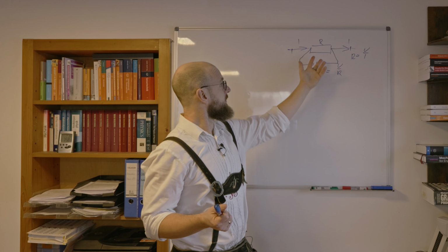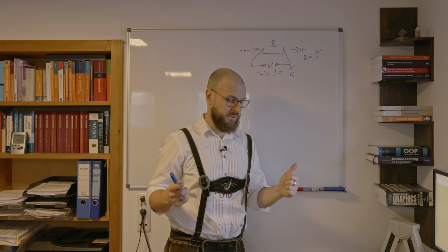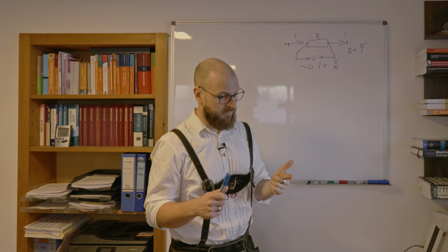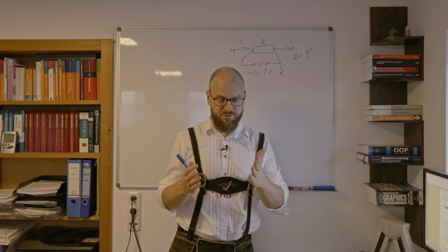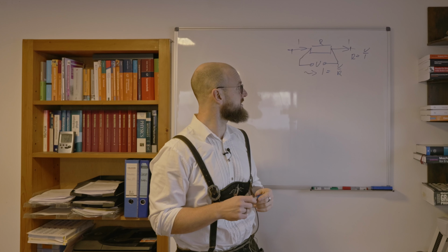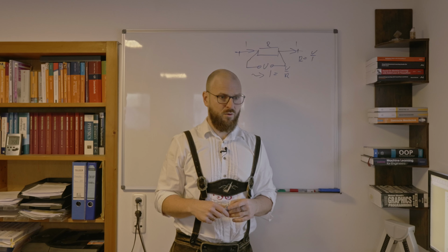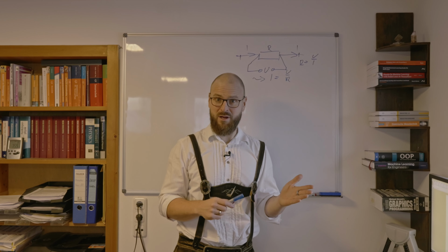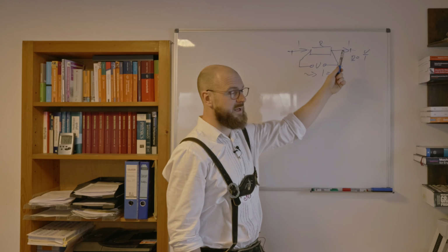What else to say about that way of measuring currents? It's flexible. We can measure AC voltage, AC currents, DC currents. There's good dynamical behavior. There's no reason which should reduce the possible dynamics of the system, meaning the frequencies we can measure with this system. So overall, it's a very, very good way of measuring currents, with one little fact which is bad about that way of measurement, and that fact is we have to build that resistor into the electrical network.